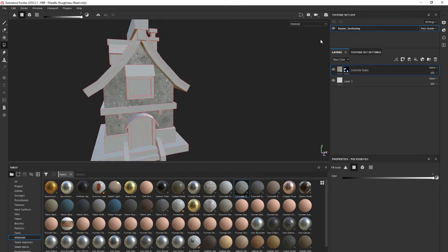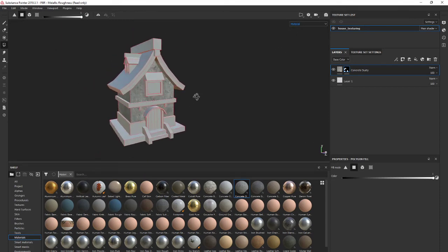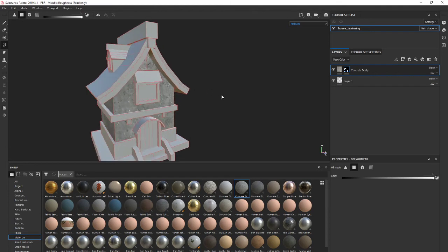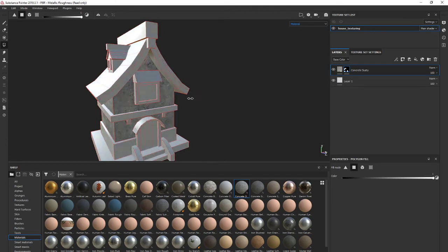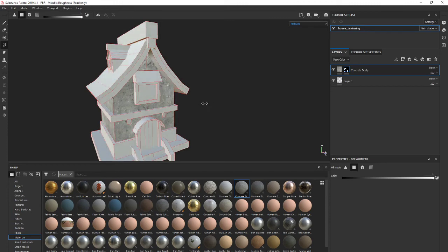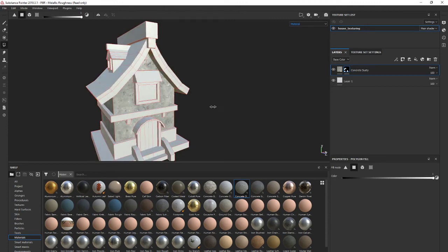Okay, so here is another drop down menu. If you press here, you will see a lot of different types of viewport. Right now we will see everything in material view. That means that all the shaders and everything work correctly, and if you press shift and the right mouse button, you can rotate the light source to see how everything looks with different lighting.